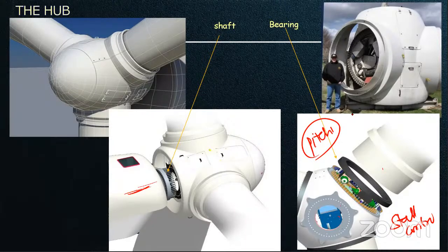The blades are usually made of materials like glass fiber reinforced plastic, GFRP, or polyester. Glass fiber has hair-like structures. They place it in the mold according to the strength requirements. The polyester resin is then applied to reinforce it, and once it dries, it becomes a solid material.